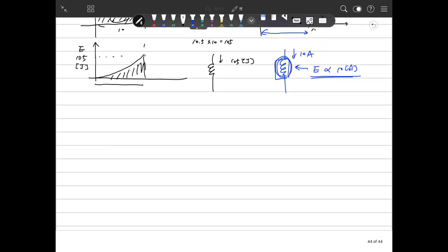So we will think about it more simply by equation. P is VI, that means L di/dt times i. To calculate the energy, we have to integrate: the integral from t0 to t of p dτ. What's the meaning here?